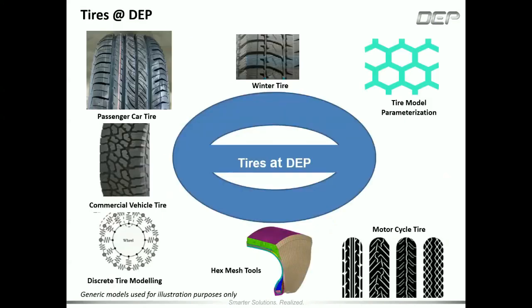So now with respect to tires, tread patterns are obviously very complex in nature and modeling can be a very time-consuming process depending on which configuration needs to be studied. The tool set in MeshWorks will also help in creating discrete models which can be used for low-frequency analysis, and MeshWorks also plays a very vital role in model parameterization. Different models can be created to assist with the tuning process to ensure that the engineers can get a better correlation between analysis results and the physical testing.